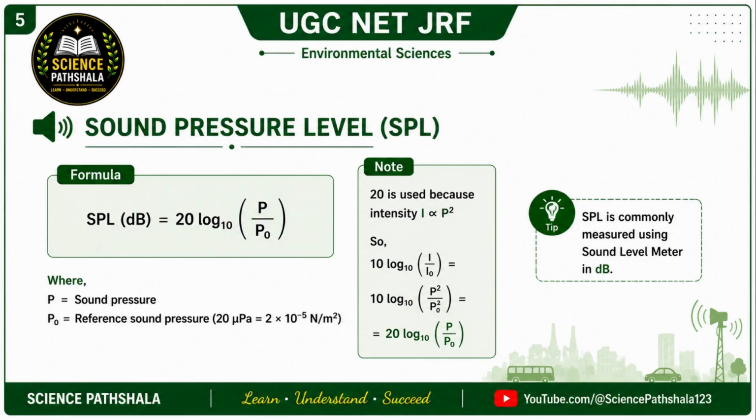Now let us study sound pressure level, commonly called SPL. The formula for SPL is SPL equals 20 log P divided by P naught. Here P represents sound pressure and P naught represents reference sound pressure. The standard reference sound pressure is 20 micropascal. Now an important question arises, why do we use 20 in this formula instead of 10? The reason is very simple.